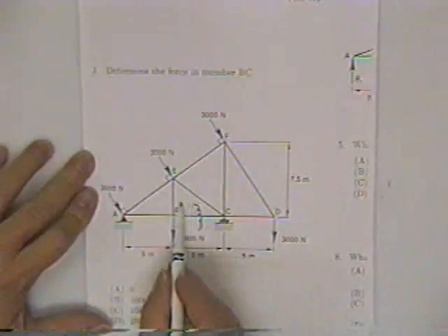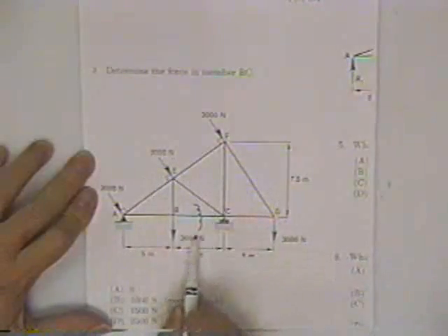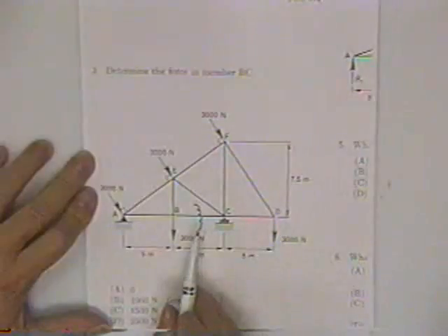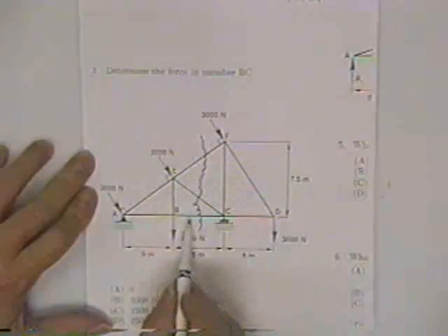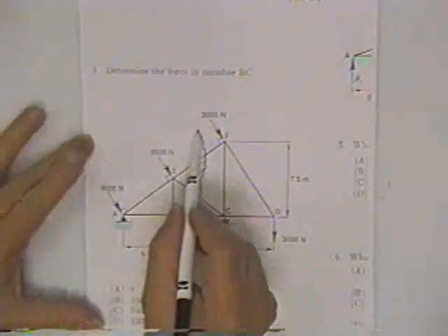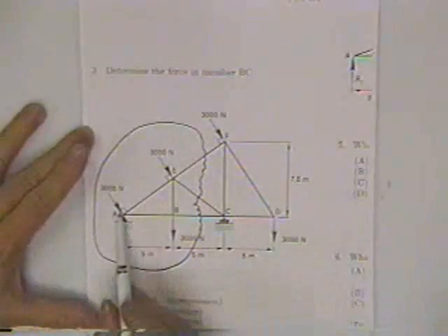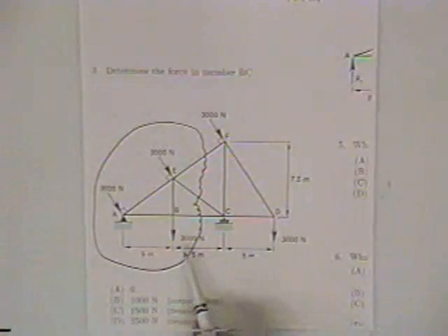If you don't cut it, you won't be able to see the force inside there. Now you could cut around here and around there and around there if you want to. But every new member you cut adds one unknown to the problem and increases your grief proportionally. Cut as few members as you can. I see I can cut 3 members, and then I can come on around either end of the structure that you want to. It doesn't matter. That's what you use for your free body.